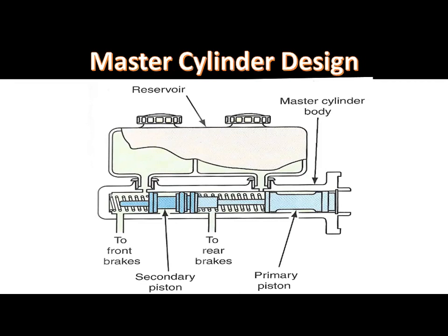If the brake shoe adjustment is not correct or air enters the brake system, excessive brake pedal movement is required to apply the brakes. Under this condition, the driver may pump the brake pedal rapidly to apply the brakes.